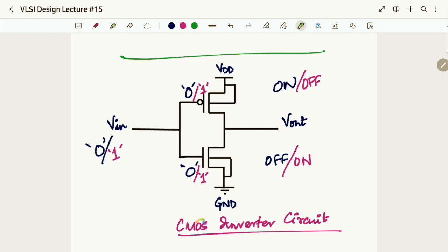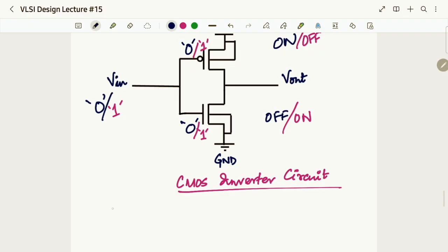So because of this, it is termed CMOS inverter. Now tell me, if I am bifurcating the work on my PMOS and NMOS, that means my power dissipation will be low. See, power will always dissipate, but our focus should be that it is low. Lower than whom? The predecessors of CMOS inverters. So power dissipation is low.